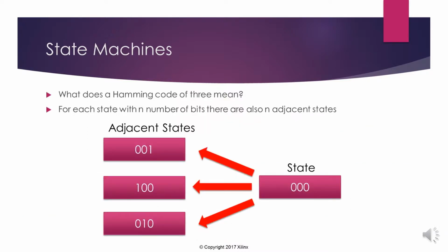Now, if we need to keep operating, then we have two options. We can implement 3 of the state machines in TMR and vote on the outputs of the state machines, or we could implement something using a Hamming distance of 3 between each state and then map in the adjacent states. We're going to look at TMR in a little while, but let's take a quick look at what mapping these in with an adjacent state of 3 is.